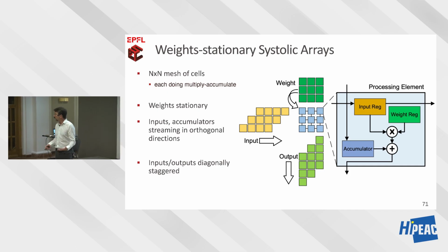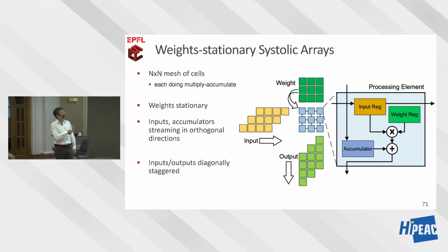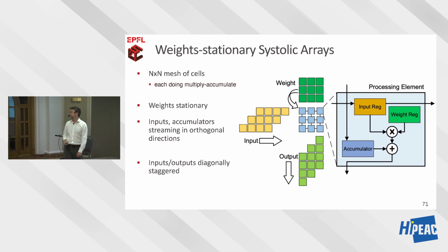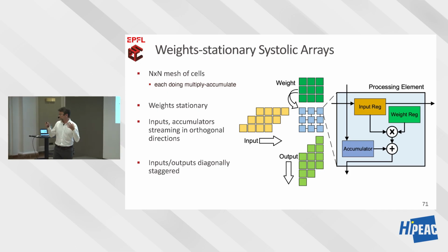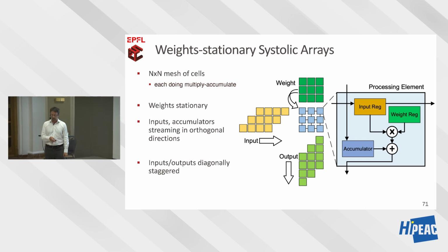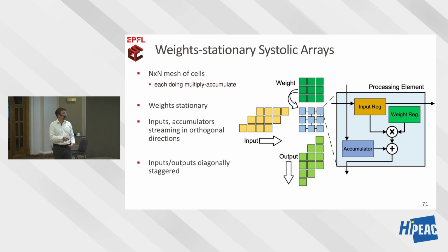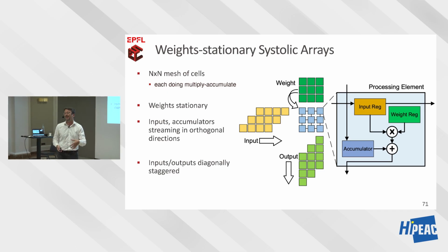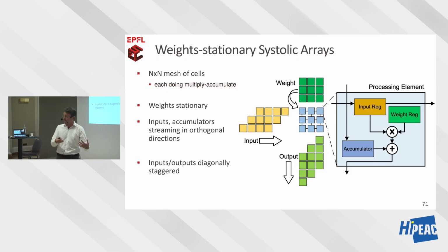If you just do the math on this connection, you see that by storing the weights inside the weight register and keeping them constant, then we can stream in a stripe of inputs and compute a stripe of outputs at the output. So it is a very simple and very compute-intensive type of accelerator, and the basic implementation of something like this can be done maybe in a few days. Then the devil is how to integrate it, how to optimize it, etc. But the main machinery is very, very simple.